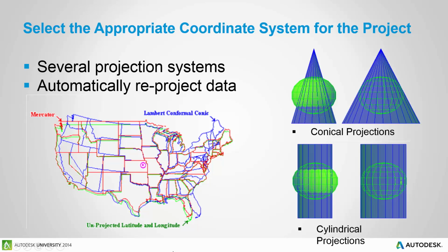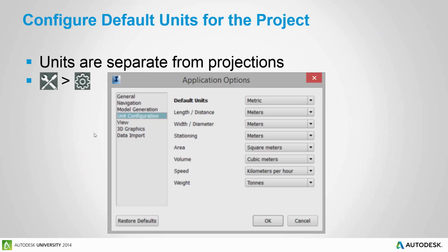You'll see that I have 3 different coordinate systems here, and right at the center point where that data is aggregated, it's pretty accurate, but as you get further and further out, it becomes less and less accurate and it doesn't line up as well. So that's why it's extremely important to make sure you have the projection system set before you even begin.